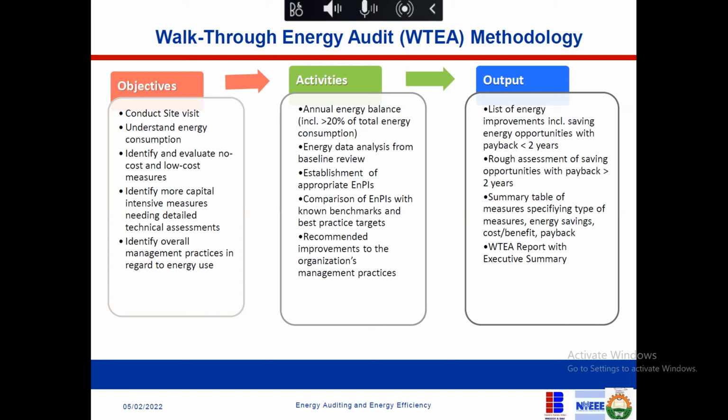Then what activity are you going to carry out? You are going to do energy balance. This might be too much for now. Energy analysis from baseline review. You look at the baseline review, right? For instance, if it's a hotel, when they have high occupancy, the energy is expected to go up. But when you see high occupancy and energy is going down, or when you have low occupancy and energy is going up, that should be a red flag. And you notice and observe.